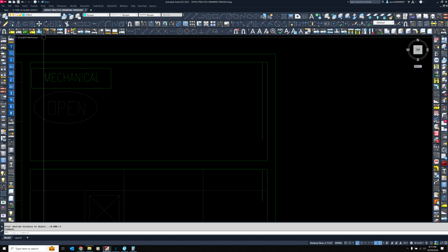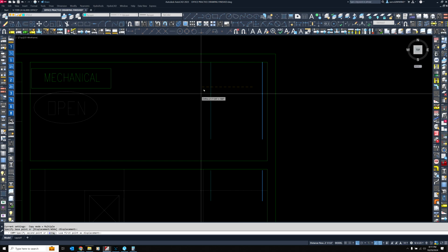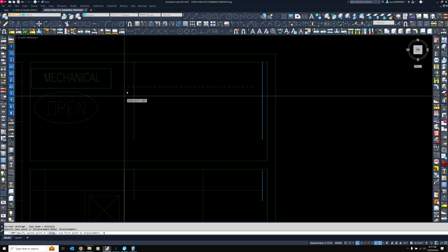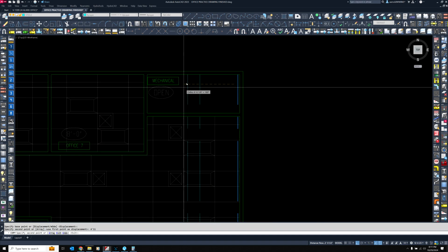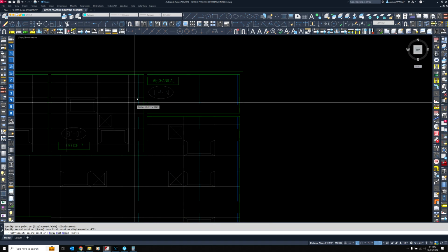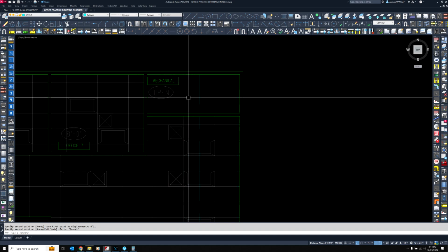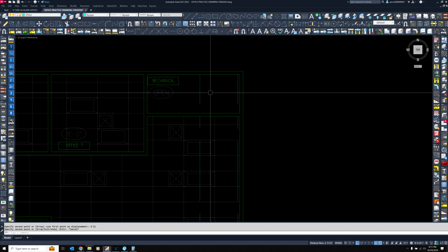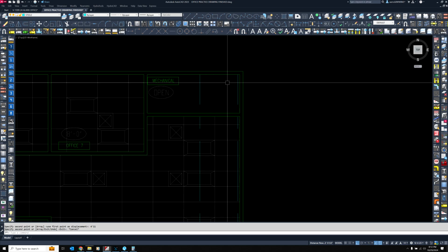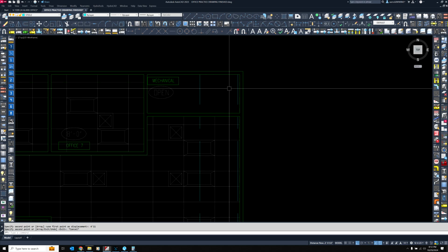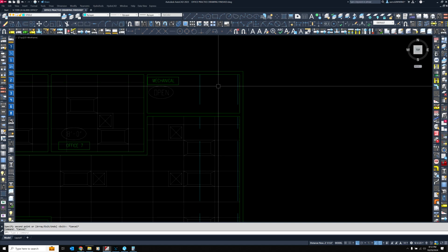We can do this by actually using the copy command. Left click, enter, left click, and type 4'11 inches, enter. And then you can try to get smart with it and go 9'9", but we're not doing that. Adding feet and inches when you're used to doing tens for whole numbers. Practice it, you'll get better at it, but there's always a risk of screwing that up.